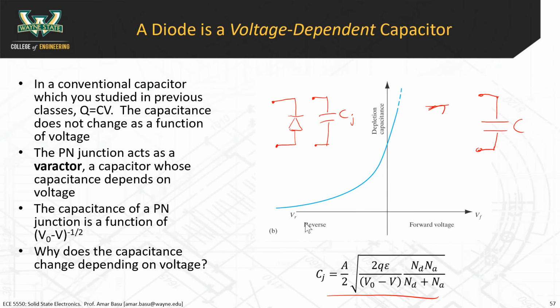You have these optical signals that are coming in at gigahertz speeds, and you want that photodiode to be able to convert those optical signals into electrical signals. So that's all the information so that you can browse Facebook. So in those cases, often those diodes are reverse biased so that you'll minimize the depletion capacitance and the diode will be able to work faster.